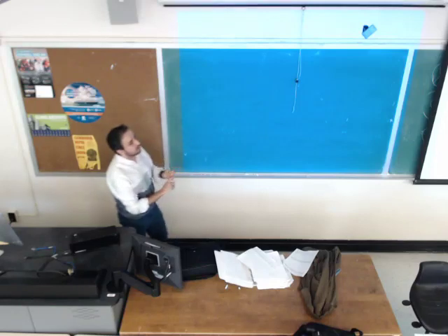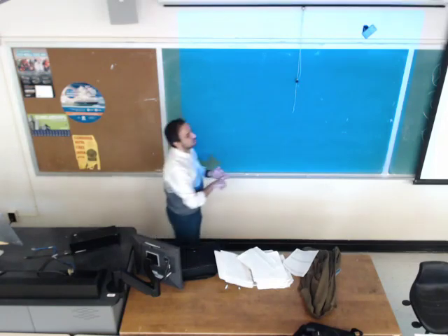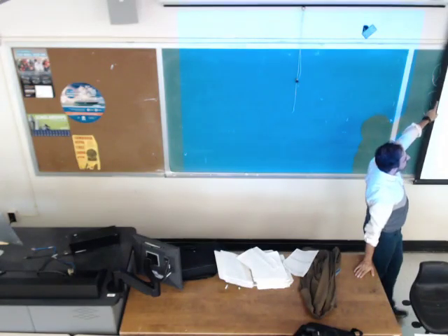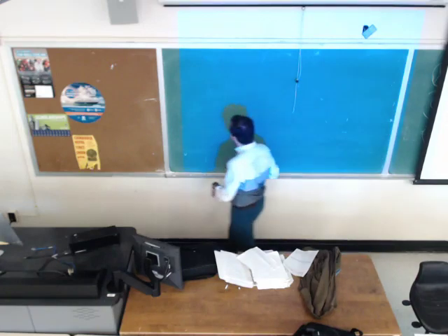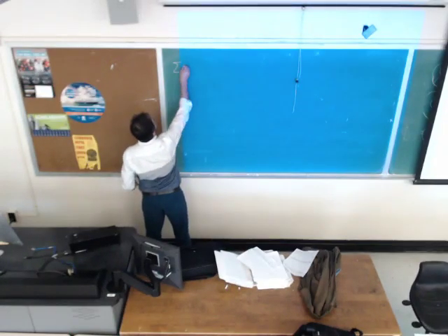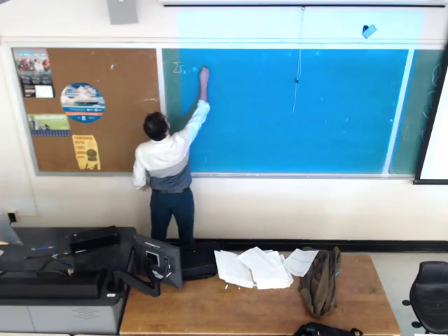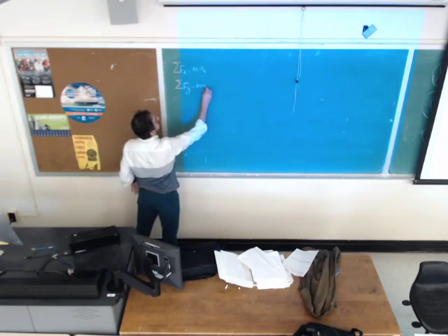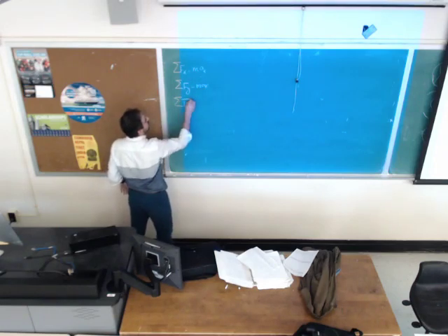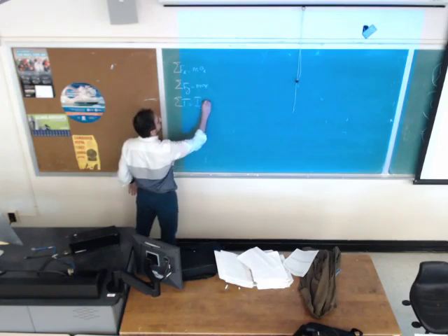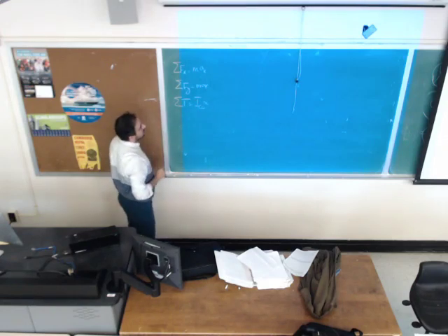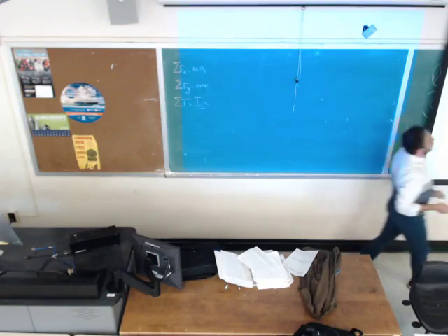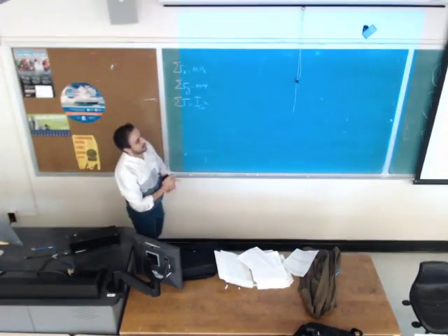Three equations meaning force in x direction equals mass times acceleration in x, force in y direction equals mass times acceleration in y, and torque. I'm talking about this. Sigma F in x direction would be mass times acceleration in x. Sigma F in y direction, mass times acceleration in y, and summation of the torque is going to be I with respect to the center of gravity times alpha. So each link is going to provide three equations. Three moving links, we are going to get 9 equations, and we are going to have 9 unknowns as well.